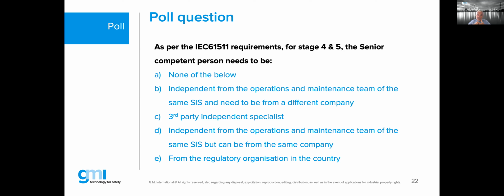That question is probably confusing coming from the manufacturer background, which is from IEC 61508, because there that would be very true. But for our topic today, IEC 61511, the independency is totally irrelevant to what level of SIL you will try to achieve.